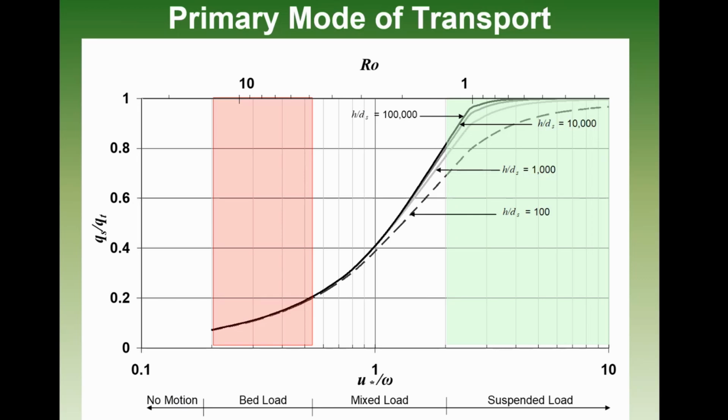And if it is 1, that's what I love. At 1 here, you get 40% in suspension and 60% as bed load. So here's the way I think about it, which simplifies my life greatly, because sediment transport can be a nightmare, really. You calculate your shear velocity. Shear velocity is a measure of turbulence, right? So you get a certain scale for the vibration of the fluid itself, okay? That is our U star.